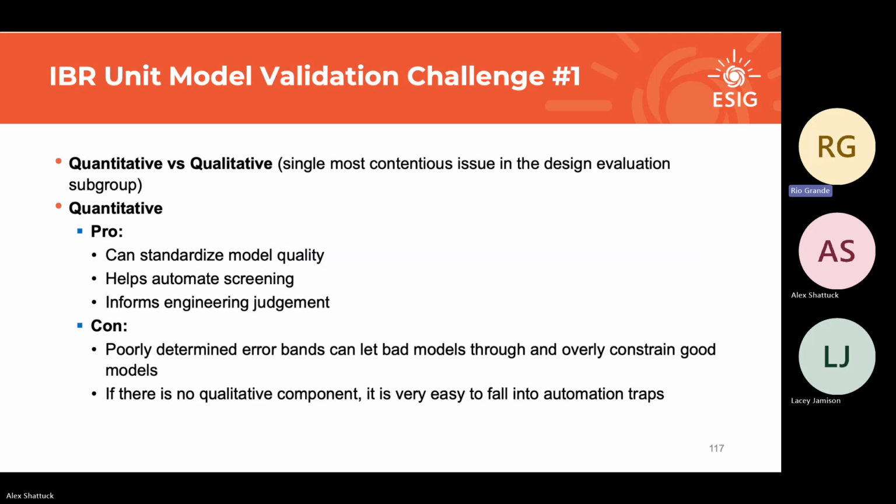No one can meet that small percent of load variance. Maybe that was intentional, maybe it wasn't, but the end result was a load smoothing criteria that no one can meet, which means no interconnections. If you say with your model validation that you need a 2% model, you're probably not going to get that from anybody, which means no one's going to connect. So it's really important to have some judgment, know what's out there and how it works, so that you don't overly constrain everything.